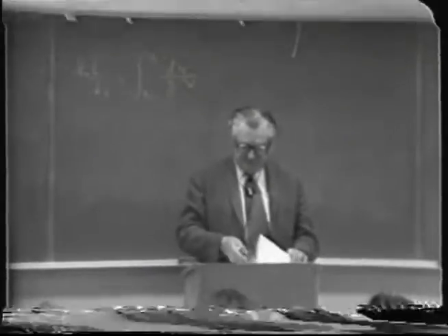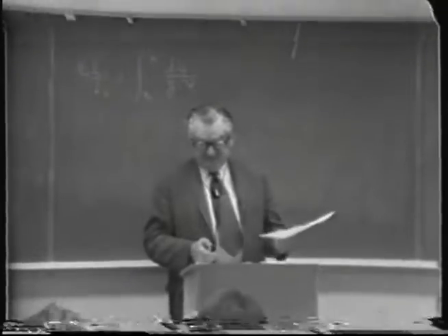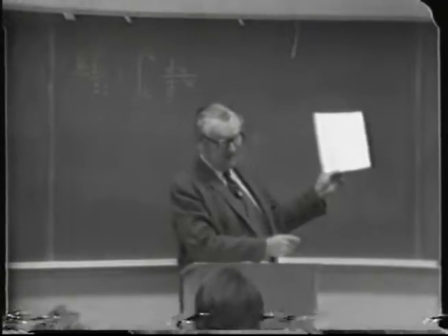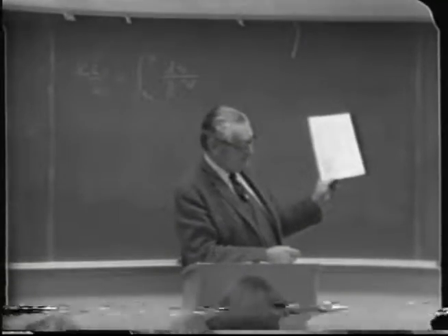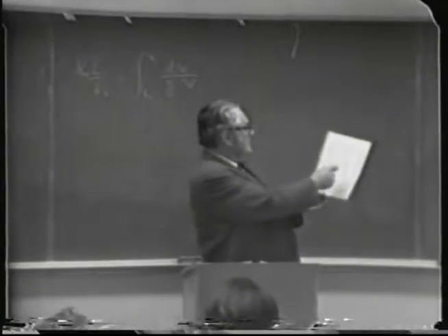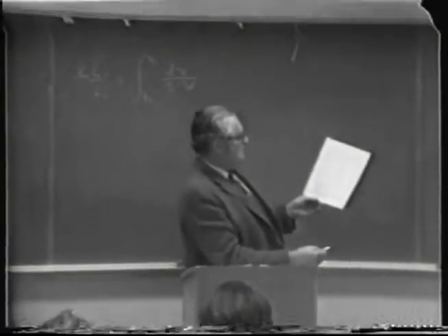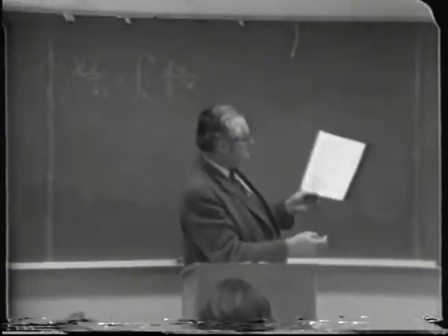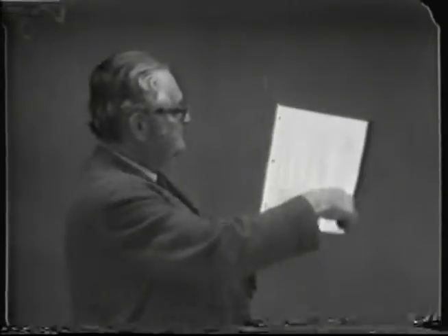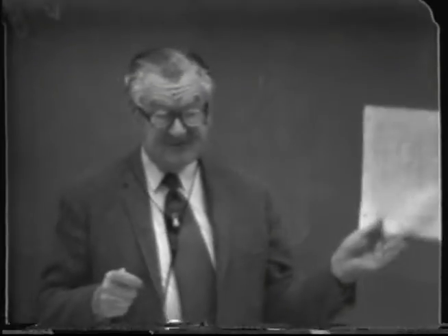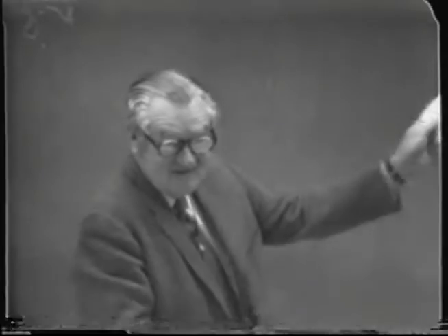Now I think you'll recall that when I handed out this table earlier in the quarter of the equilibrium data for ethyl alcohol water mixture at atmospheric pressure, I wrote in longhand in the last two columns the function of y minus x on a weight percent basis, or mass percent basis, and the reciprocal value. So I've already worked out for you the function necessary to plot this curve.